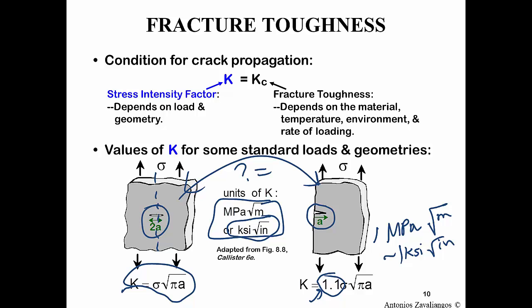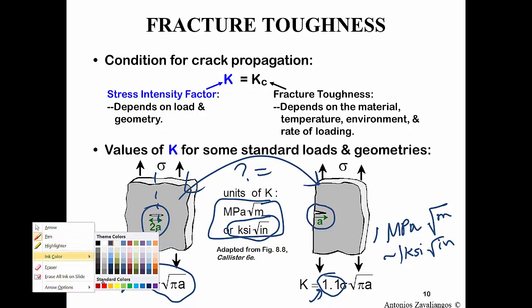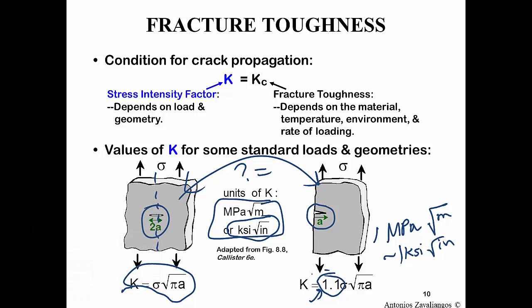There should be no reason why the surface cracks of the same geometry should have an increased stress intensity factor. In fact, this 10% higher number means that a surface crack is more dangerous than an internal crack, because for the same geometry a higher stress intensity appears.